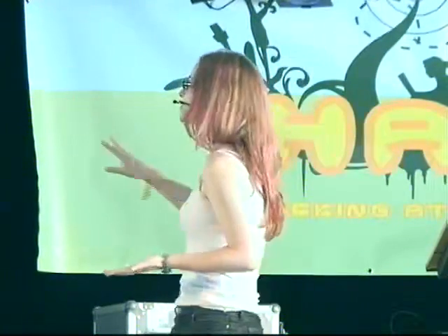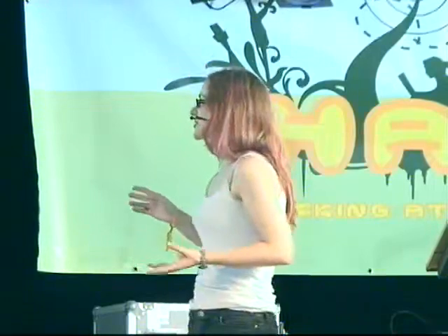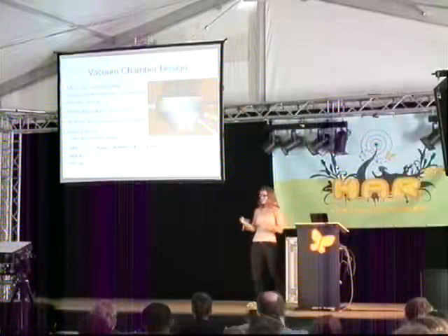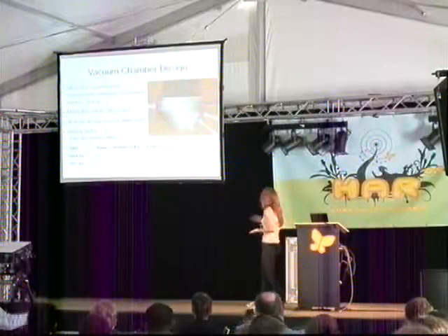Now, just talking about those two parameters, Young's modulus and yield strength. Young's modulus is effectively the springiness of the material. It's like a spring constant. And the yield strength is the stress at which the material first starts to deform plastically. So it deforms and it doesn't spring back into its original shape. So those are useful when you're considering safety factor.